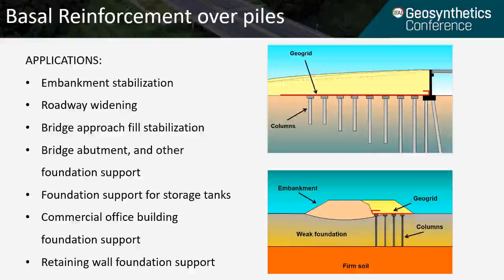Because the most critical aspect when designing a column-supported embankment is that the load must be transferred effectively to the columns to prevent punching of the columns into the soil structure and avoid severe differential settlements in the surface of the structure. So the spacing in between the piles is very crucial during the design of this type of solution.